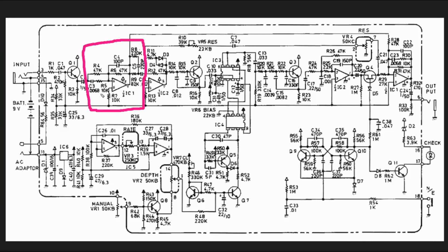It's a trick to help increase the signal to noise ratio so that we don't have a really hissy sounding delayed signal. On the output though, you'll notice that we have this resistor in parallel with a resistor and a capacitor, and that actually functions as a single pole low pass filter before going into this next op-amp stage. And we'll actually see here in just a little bit why they decided to put that in there.